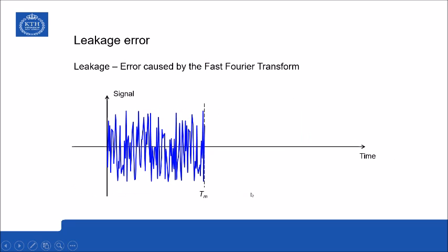And in this case, where we have a random-like signal, then we apply a weighting window called the Hanning window. And in principle, this is a sine square or cosine square signal, and it is 1 in the middle point here, and it is 0 at the end points.